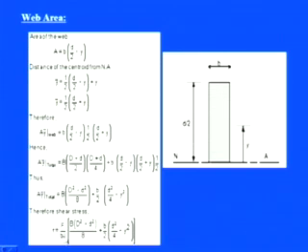So this is F divided by b into I, and now this is b into d square minus d square by 8, plus b by 2 into d square by 4 minus y square. Now you see we have the shear stresses in that way. If you look at those pictures, you will find that it is again going in a parabolic path, because the square terms of d square by 4 minus y square are there. So it always reflects the parabolic distribution of the shear stresses along the I section.